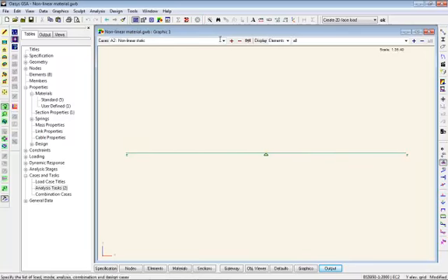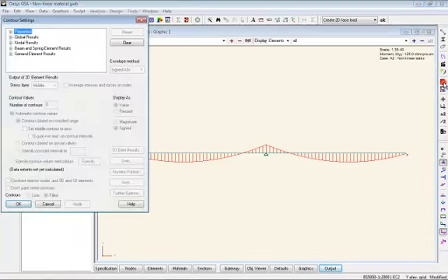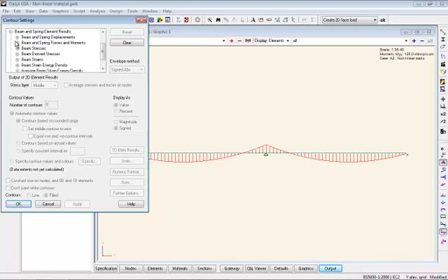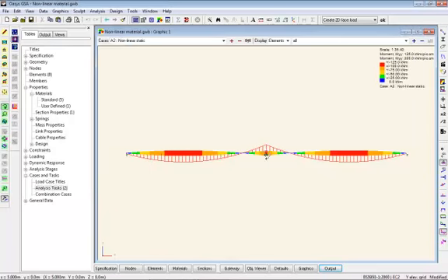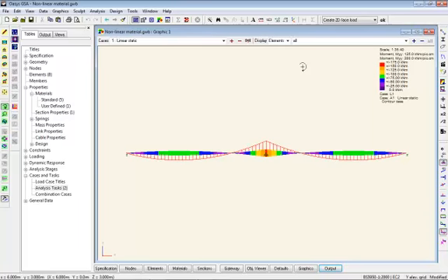The end results, I've got the linear bending moments. You see the linear elastic high hogging moments. The non-linear, the sagging and hogging look pretty much the same, and we can check this maybe by calling up the contours and just set the magnitude. And yes, you can see the hogging and sagging moments are the same. The section has yielded, got plastic hinges at the support and the mid spans as well. Whereas linear, as we expect.